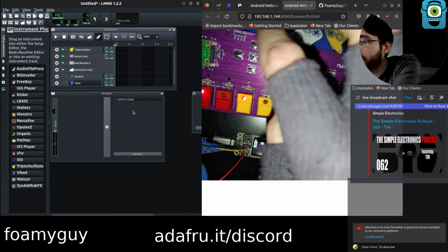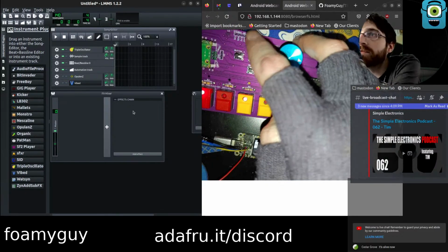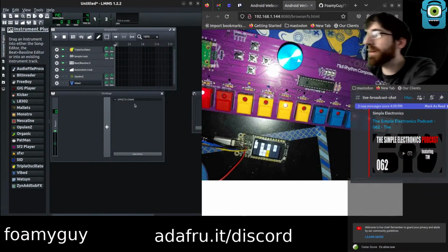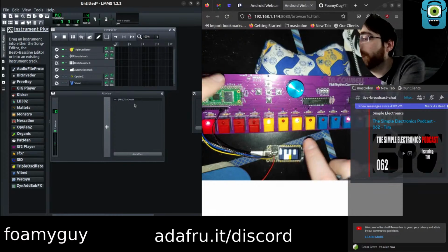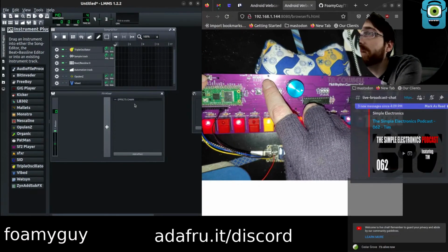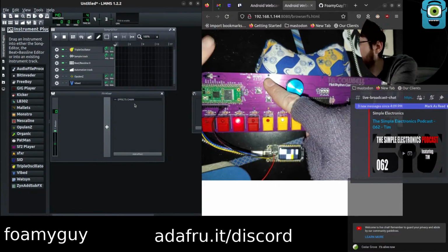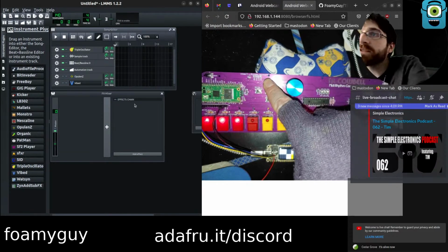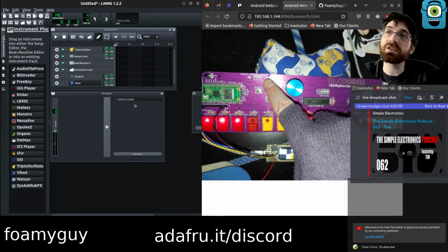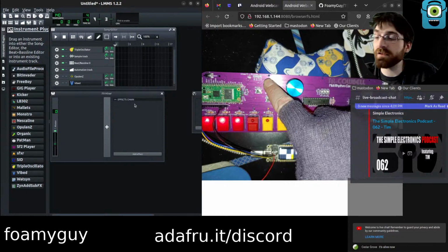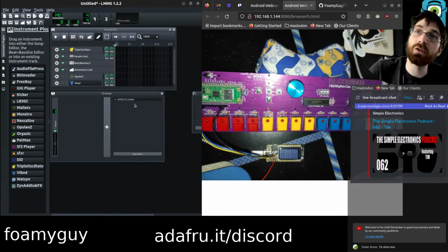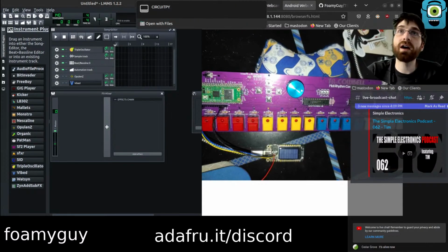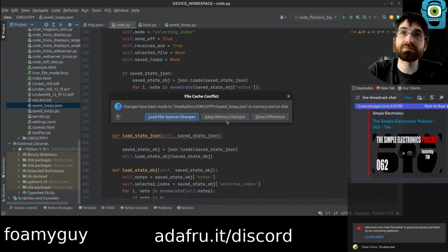And what I'll do is, instead of actually disconnecting, reconnecting, I'm just going to reboot with the reset button. But I am going to hold the up button, which now means that the storage is going to be writable to my computer. So I'm going to hold up, press reset, and then keep holding up until the thing is up and running all the way, because I just need to make sure to be holding that down during the boot.py execution, essentially.